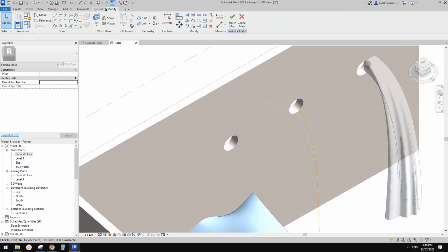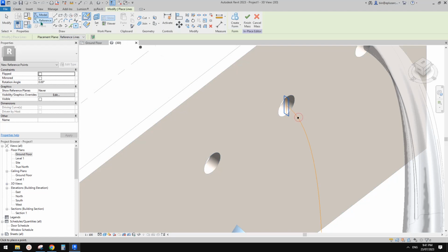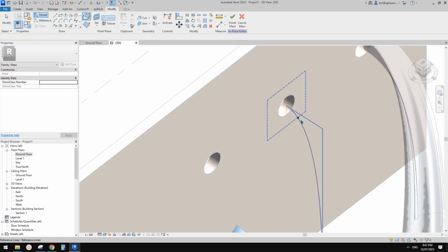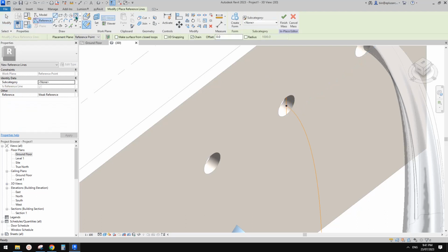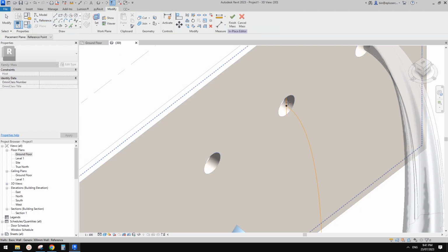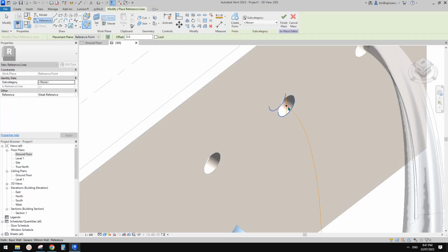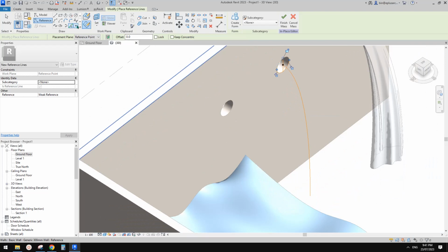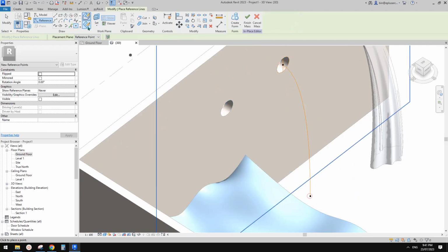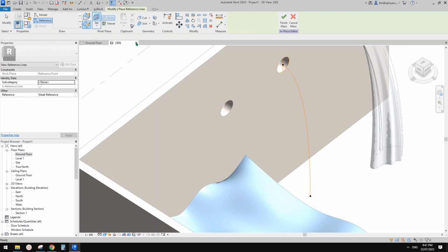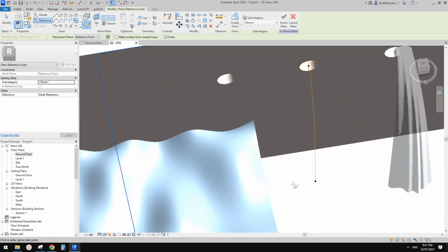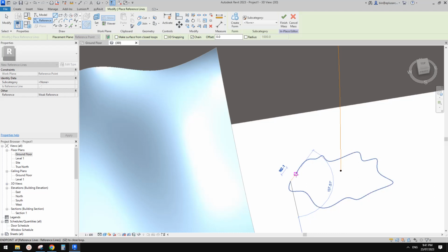path, and then we can just quickly place a point, use draw on face. Okay, and then drag this to this end, reference circle. Oh no, maybe we can just pick line and set work plane, pick the work plane of that point. Then we can pick this edge and then place another point here and spline, draw on work plane, set work plane, pick this, and then we can just create something and then just finish it with another line, tab SE to easily snap the end point.